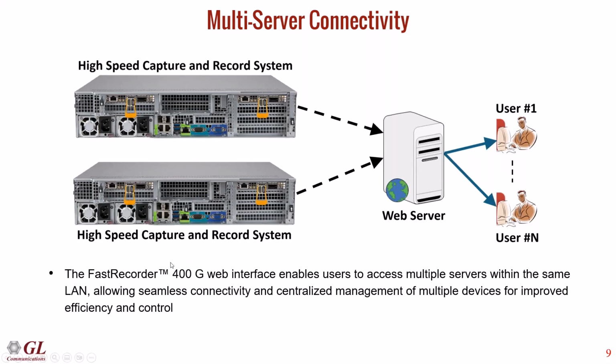You can deploy as many of these systems as you want across the network, as long as they can talk back to the web server. So you'll notice that these systems have their own built-in Ethernet port. It's a gigabit Ethernet port, and that Ethernet port is for remote management only. So you connect that into the network where it can talk back to the web server. That Ethernet port is not for the high-speed capture. That Ethernet port is for management. And so you connect it back into your network, and then from the web GUI, you can see all of your systems in real time.